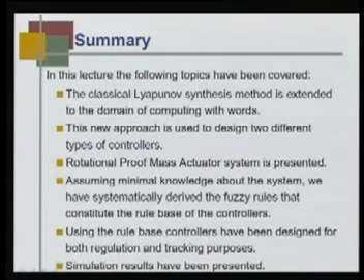So, finally, the summary. In this lecture the following topics have been covered. A classical Lyapunov synthesis method is extended to the domain of computing with words, that means qualitatively how we can use the rate derivative of the Lyapunov function in such a way that the rule base can be generated. This new approach is used to design two different types of rule base. The controller is the same fuzzy logic controller, Mamdani type.